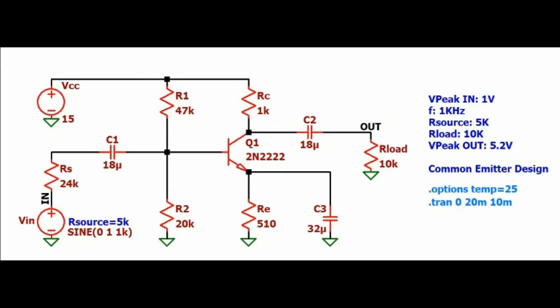First, we have to assume that the maximum collector voltage that could exist by the voltage divider that can be seen in the circuit is half the source voltage, that is 7.5 volts. In the same way, the same is done with the maximum collector current, which comes to be 5 milliamps. And thus, being guided by the datasheet, it can be established that the base current will be approximately 25 microamps.